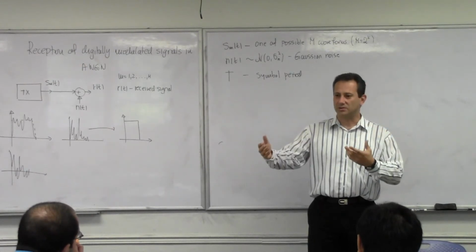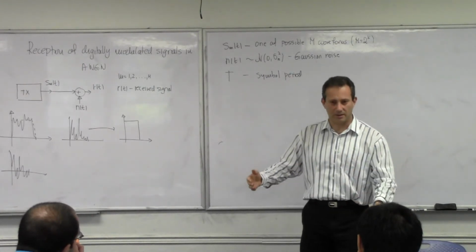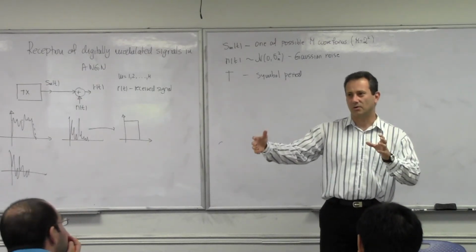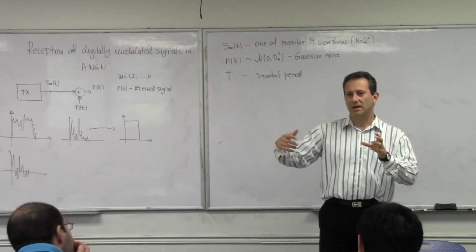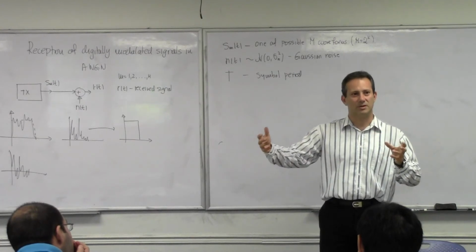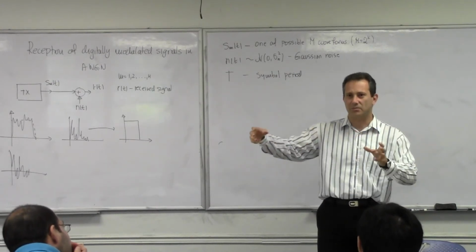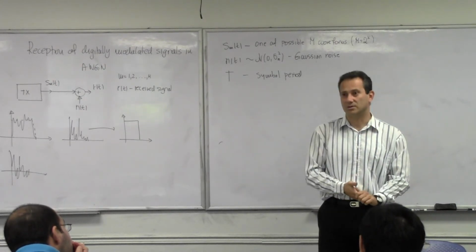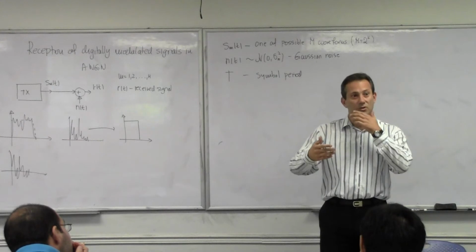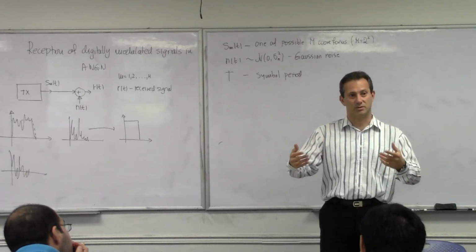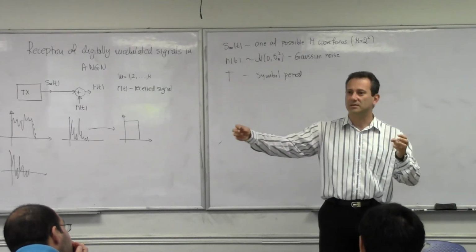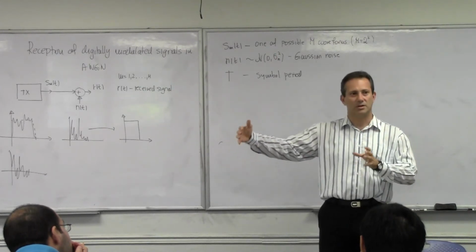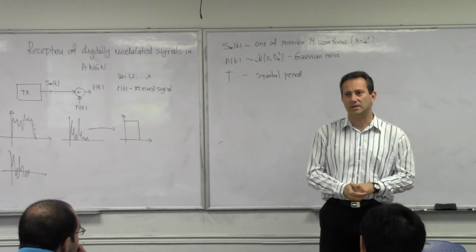Well, I'm sending you a text, so you may wait and try to recognize words as a whole. Therefore, you're going to have fewer errors, because even though some letters in some words may be erroneous, when you look at a word, you may recognize the word as a whole. And that's what error control coding does for us. It introduces redundancy in your stream, so that when you look at combinations of symbols, some of them are more probable than the other ones.